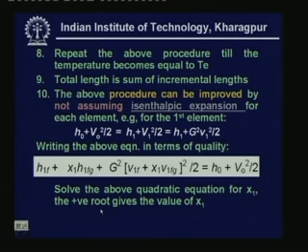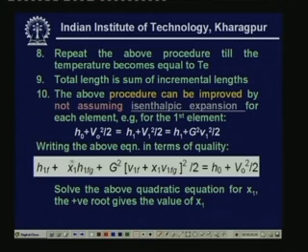So you can improve, as I said, the above procedure by considering a non-isenthalpic expansion. That means we write the energy equation also, in addition to the mass and momentum equations, like this: H naught plus V0 square by 2 is equal to H1 plus V1 square by 2, and replace V1 by mass velocity G and specific volume v1. Okay, and that equation is written in terms of the dryness fraction x1, right. So you ultimately get this equation.